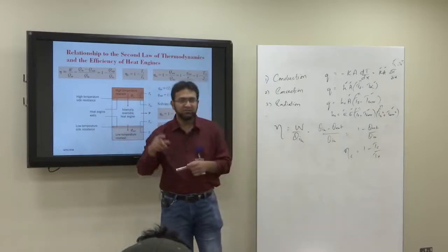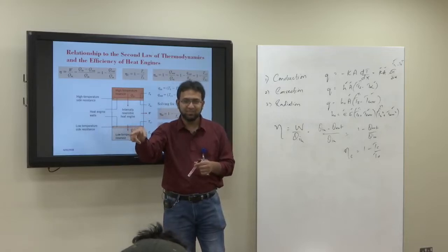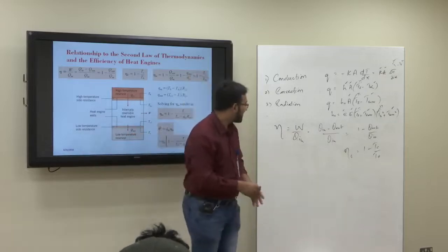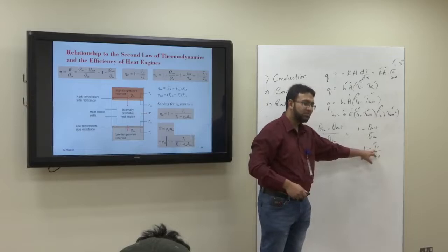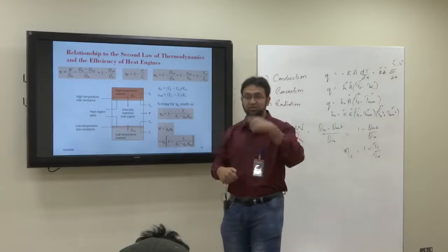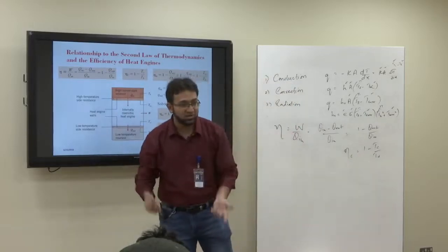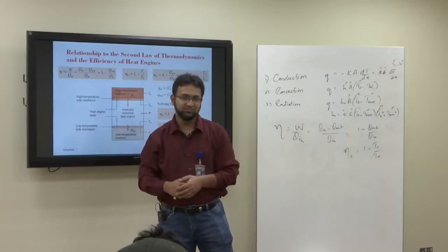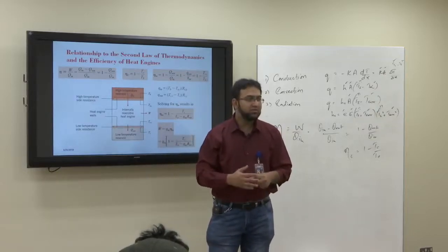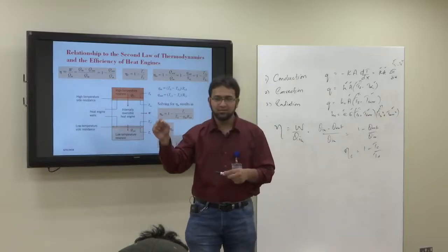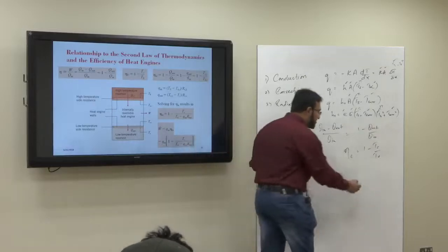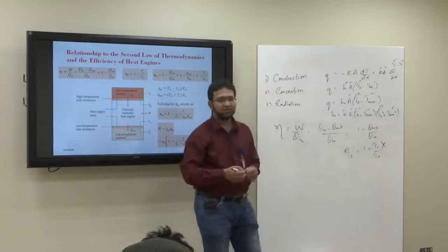Normally heat rejection is done to the sink, and in this case this room becomes our sink. But using the sink temperature here is wrong. If the condenser is also operating at 24 degrees centigrade and the air is also 24, it cannot reject heat. You need a temperature difference. So the temperature of the condenser would be slightly higher than the room temperature, so Tc is not correct.